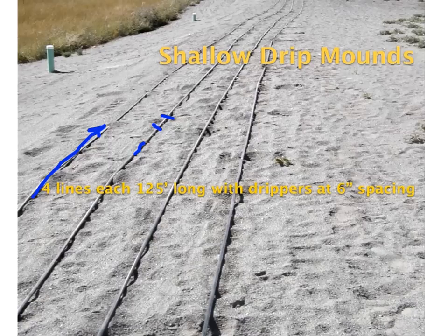Okay, so you've got a very, very small dose of effluent at each point, and you're getting a very, very uniform application in the sand because water doesn't move sideways by capillary action very effectively in sand, but there's 6 inches between drippers and it only has to move 3 inches, which isn't very far. So he's got very, very efficient coverage, and these are monitoring wells.